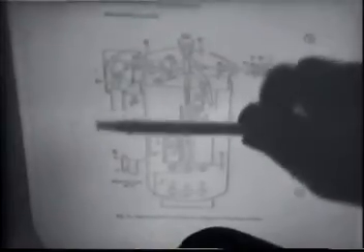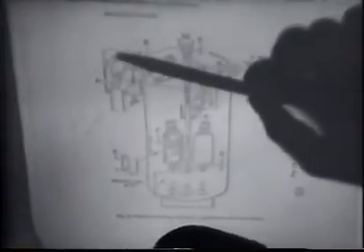The linkage to an operating compartment that houses really the power source is usually mounted at one end of the circuit breaker. As you can see, mounted in this position here, so that any power source here is transferred or translated through the gearing here to move the contacts in an up and down motion.